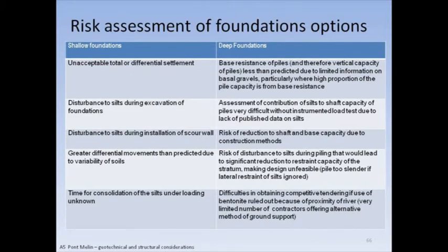We would have pretty much had to construct a very large, very deep foundation, which would obviously have been impractical. And fundamentally, we also had concerns about, if we had gone down the route of providing a foundation that carried loads all the way through the silts, that we would have found it very difficult to find a competitive way of tendering for that.